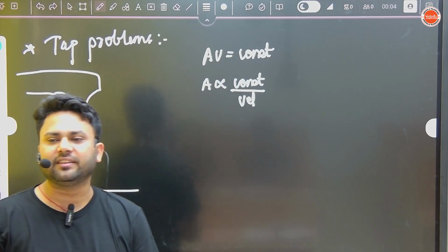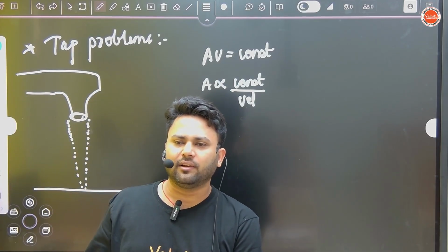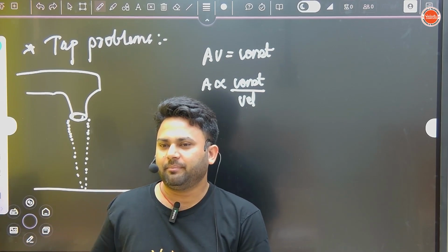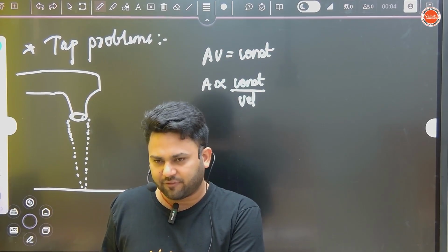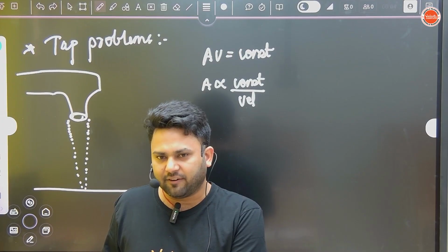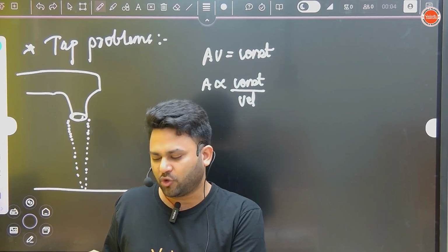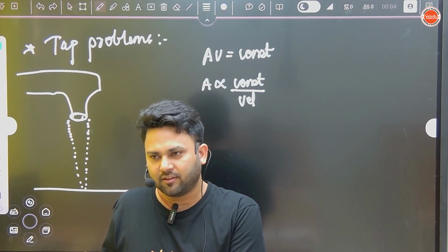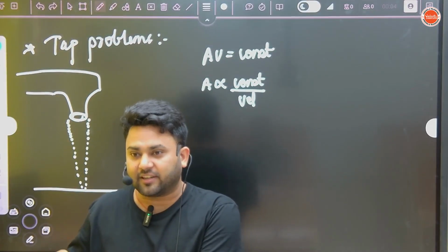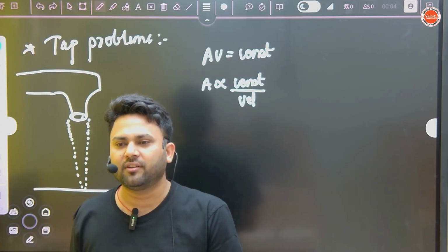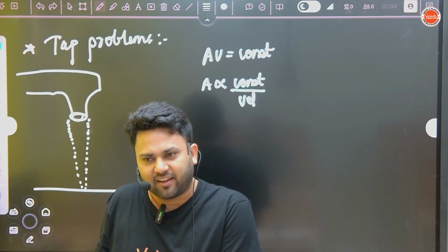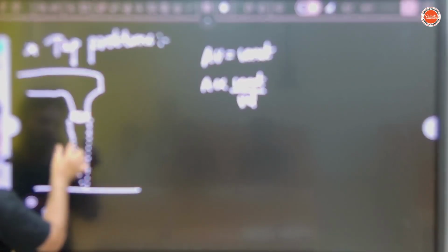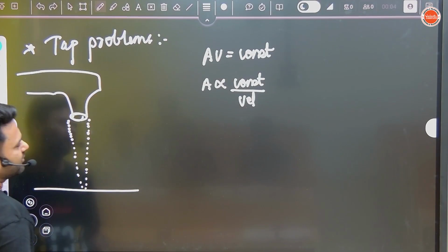Sometimes we have seen this. Suppose we are washing our bicycle or bike with the help of a pipe and water is not reaching the bike. What do we do? We put our finger, means we cover half or 25% of the mouth of the pipe with the finger. Now we will see water is reaching there. Force becomes more. Why? Because as you decrease the area, velocity will increase. Same here, velocity increasing, area decreasing.